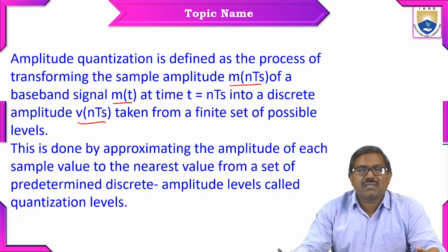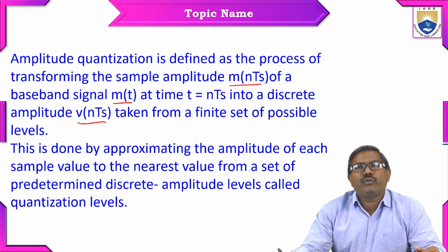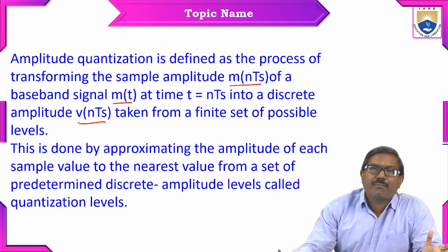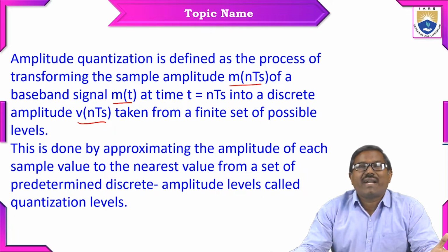It uses discrete amplitude levels called quantization levels or representation levels. These levels are predetermined. This is done by approximating the amplitude of each sample to the nearest value from a set of predetermined discrete amplitude levels.